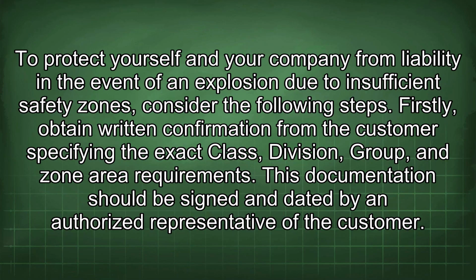To protect yourself and your company from liability in the event of an explosion due to insufficient safety zones, consider the following steps. Firstly, obtain written confirmation from the customer specifying the exact class, division, group, and zone area requirements. This documentation should be signed and dated by an authorized representative of the customer.